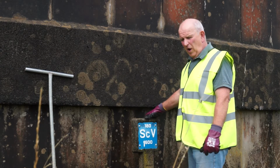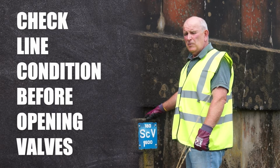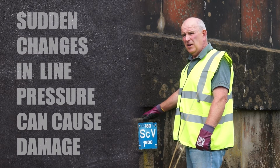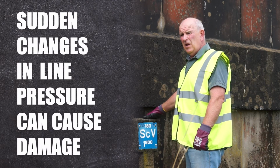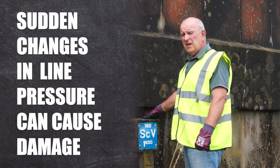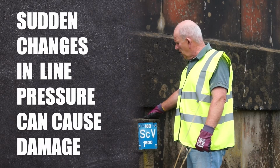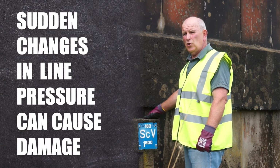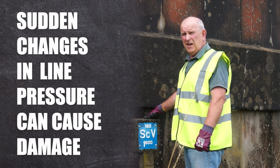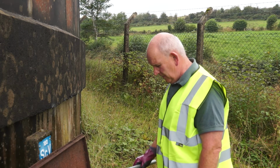Comprehensive survey of the line in question before we start the scouring process, because when we start the UDF, we are going to be lowering the pressure in the line and possibly causing a vacuum. Thereby, we would pull in any contaminants that may be in an air valve chamber. So if we have done our checks and made sure that those valves are in good condition with no surface water, then we will have a clean line. And I'm just about to start the uni-directional flushing of the line.